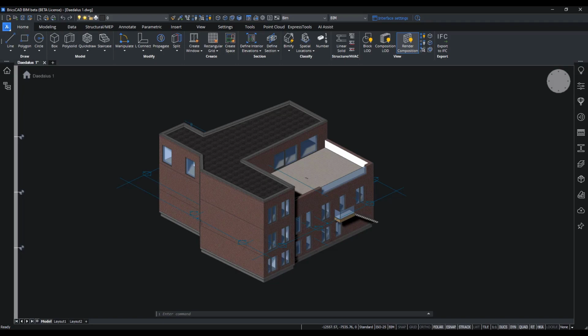One of the main benefits of the BIM workflow over traditional CAD methods is the automatic extraction of 2D documentation and schedules out of the 3D model. During the detailed design phase, a lot of documents need to be prepared. Different floor plans, sections, schedules, and material lists. Having these documents available automatically from the 3D model speeds up this otherwise time-consuming task and reduces the chance of human error. These extracted plans can be easily updated with each design change with minimal interaction of the operator.